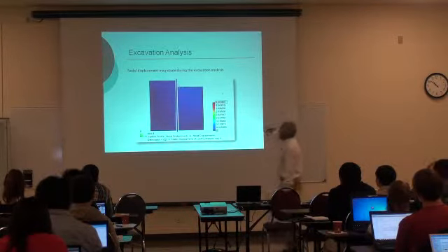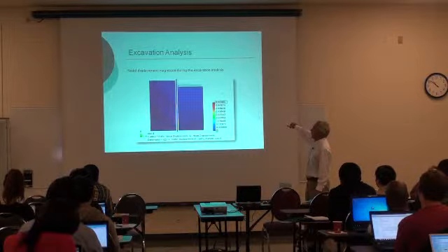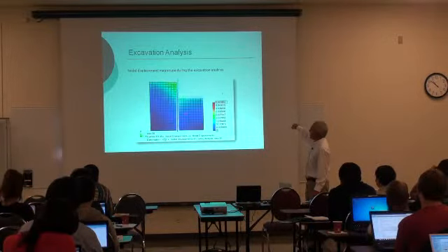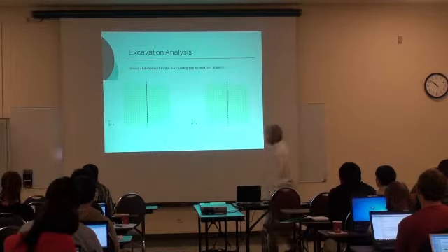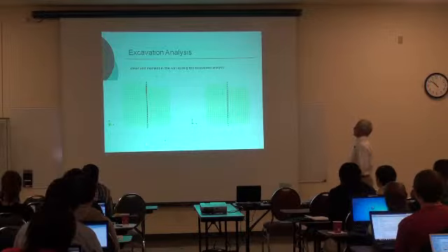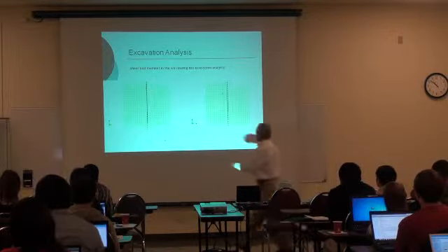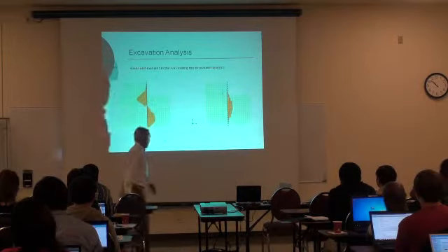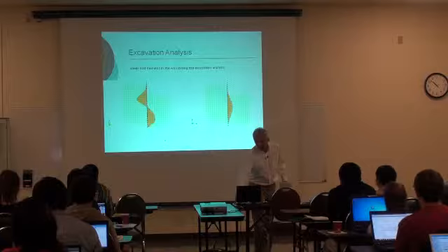Because we are using a beam element, you can look at how the demands in terms of shear and moments develop as you remove the elements. And that's pretty fun. I like this one. Because as you remove the elements, you can see how the shear demand and the bending moments develop, how the maximum develops and moves down. I thought that was very instructional and it's very useful also in practice.